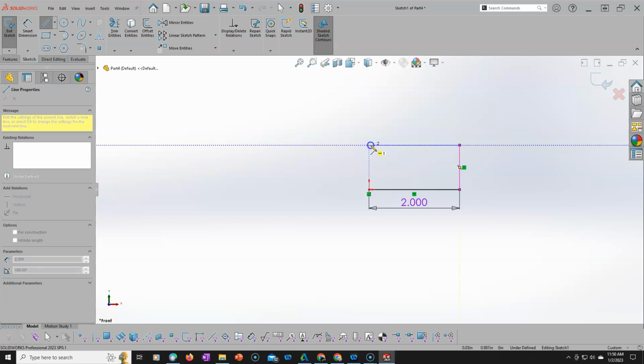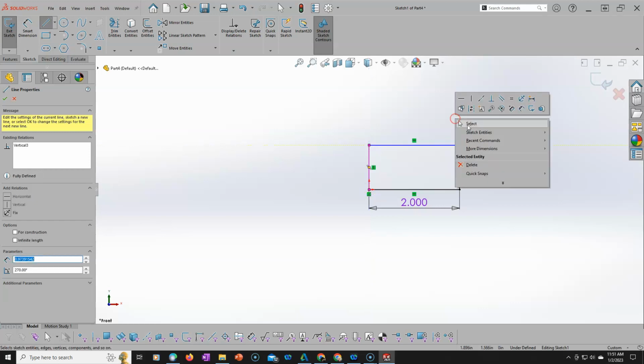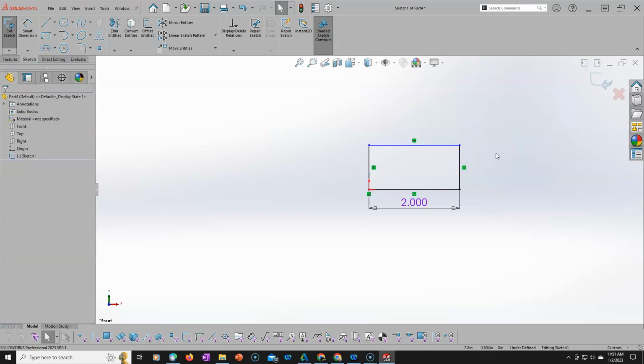All right, we come back over to the origin. I have one in yellow and one in white. The yellow is telling me that I'm going to get horizontal applied, and my inference dotted blue lines are telling me that even though I'm vertical, I'm not going to get that relation. So horizontal, and then if we go back, I get a concentric and a vertical. All right, so those combinations of relations give me a lot of response to what's going on on the screen.